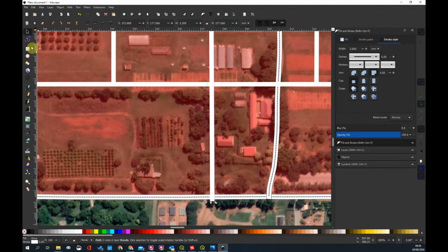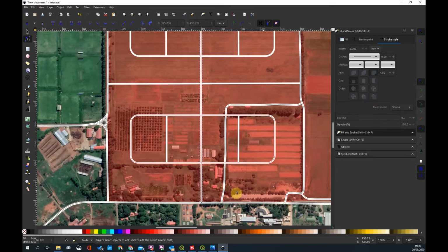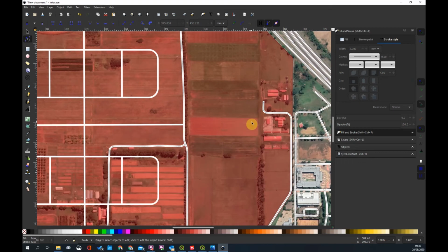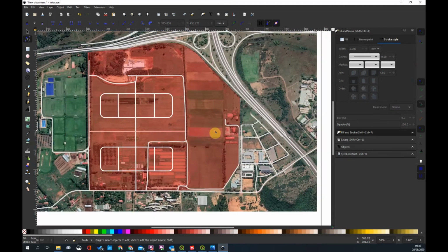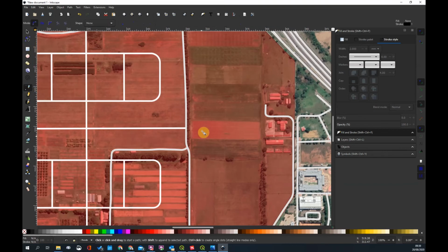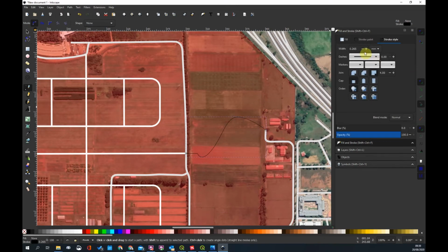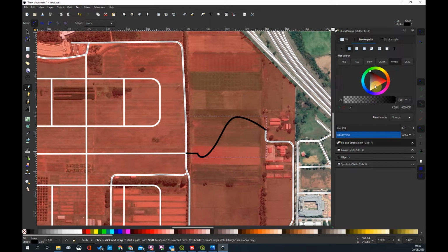So click this bit of line work, use your edit path tool, so grab the node itself. Let me just show you one last, just for interest's sake over here. So here I might create a bit of road network that'll come. So this I might just subdivide as well. So I'm going to create this path tool. I'm going to start over here, and it'll find the endpoint of a node. And if you hold down the cursor, it will start introducing curves, and you can really make a curved road work well here. So I'm going to grab the end here. I'm going to end the command. Just remember, I need to change the stroke to 2. Okay, and I'm going to change the color to white.